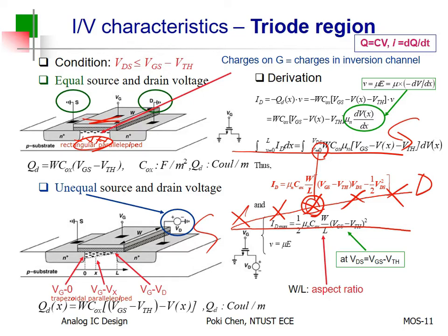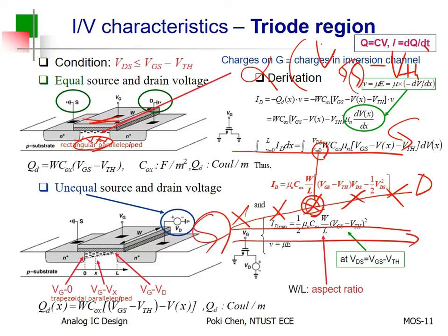Okay? And again, as I mentioned already, the channel depth is determined by VTH, right? But right now we are not talking only about the source. We try to move from source to drain. So for any point, you label it as X, then the channel depth depends on VGX minus VTH. Bingo.